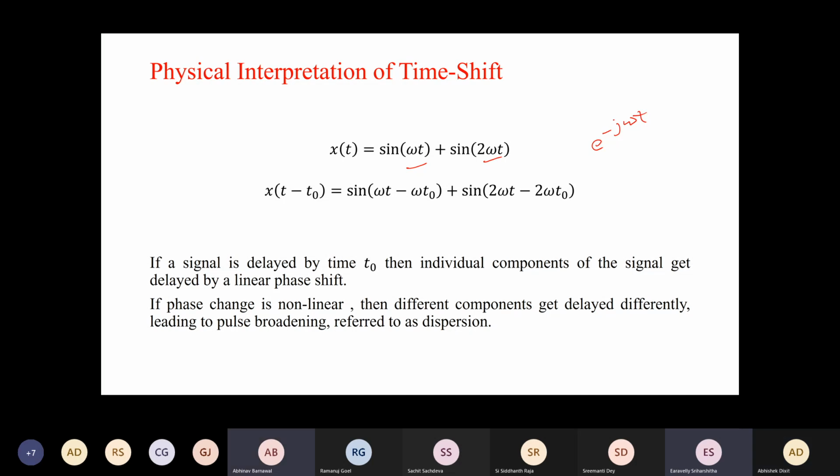So what he said was, if this is shifted by some omega t naught and this is also shifted by omega t naught, then there might be a possibility that this overlaps with this. But actually these components are orthogonal to each other, so no overlapping or cancelling is possible. Similarly, you can extend the same thing for aperiodic signals where these are the bases. And again, you can think that this is orthogonal to any other frequency, so they cannot overlap or cancel each other.